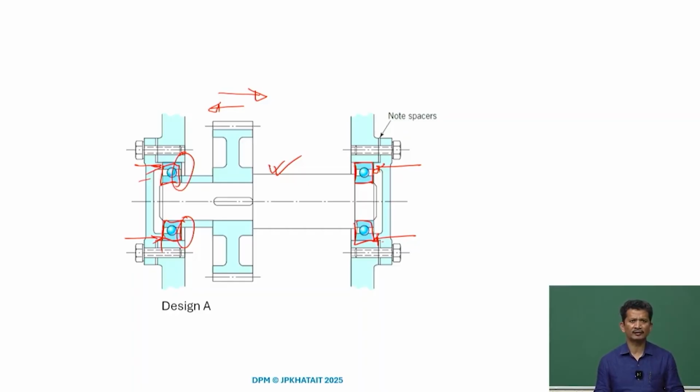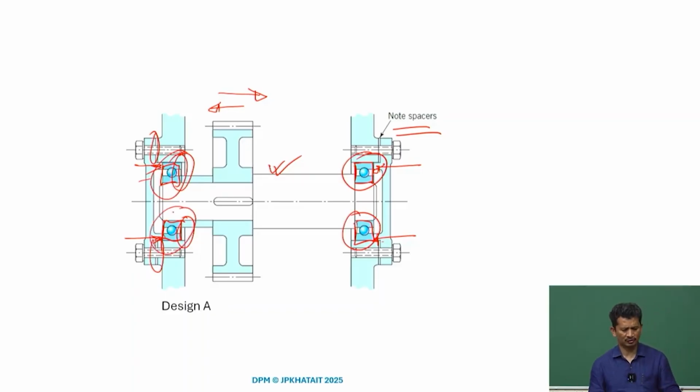But what we realize is that at the time of assembly it might be okay, and many times we call it form closure. So, we need to know exactly what the length is, and if there is any offset. Of course, we have to use spacers to get rid of any kind of clearances we have, so we can pack it and assemble it nicely. But if there is a little extra force, it will come to the bearings and it will dislodge the outer and inner races of the bearings.